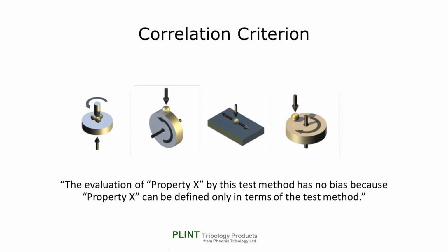Many were developed as lubricated scuffing or seizure tests for evaluating extreme pressure properties of lubricant additives. Of course, there is some logic in using like material sliding on like material if you want to produce surfaces that have a tendency to scuff or seize. The materials have mutual solubility, hence poor tribological compatibility.